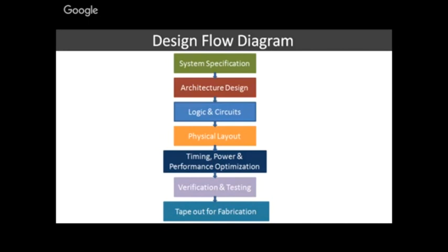But schematic becomes very difficult and complex when your circuit is complex or intricate. In that case, HDL entry is much better as compared to schematic entry. So if your circuit is complicated, we switch to HDL entry. There are two types of HDL files. One is the Verilog file, and the second one is the VHDL file. In these files, we just follow the syntax to implement your design for the application you are designing your circuit for. On the basis of that syntax, you do the entry of your design.